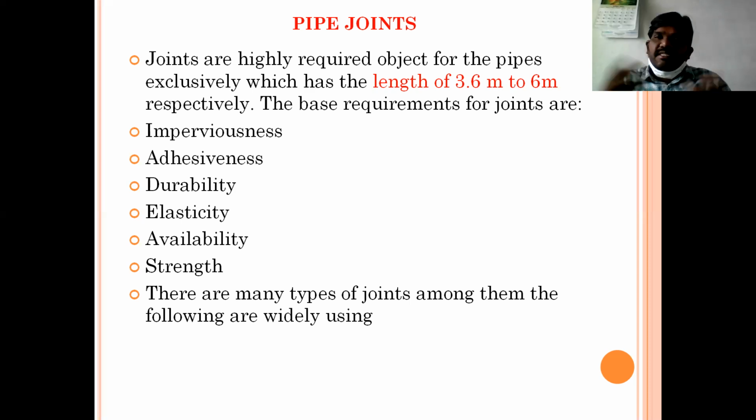If the joints are breaking every time, all your efforts go in vain. That means if the durability is not up to the mark, every time you may have to dig the soil for repair work, as we are keeping those pipelines in the ground. Before you keep those pipelines in the ground, you must select the joint which has good durability with respect to the span of the selected pipe.